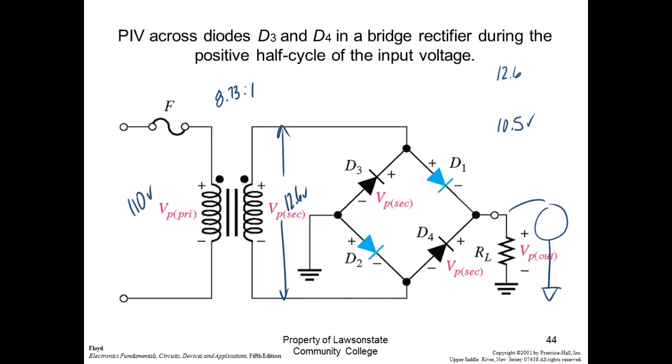Why would you call it an artificial center tap? There's no center tap there. No, no. It's acting like an untapped transformer. Understand? In fact, the commons are over here. The commons are on the diode side. They're not on the transformer side. They are on the rectifier side.